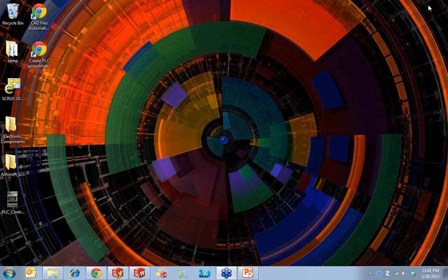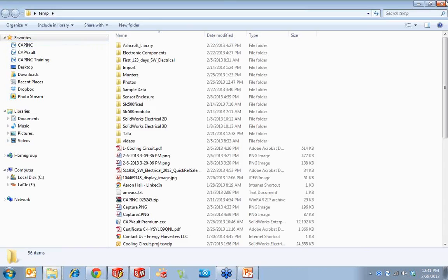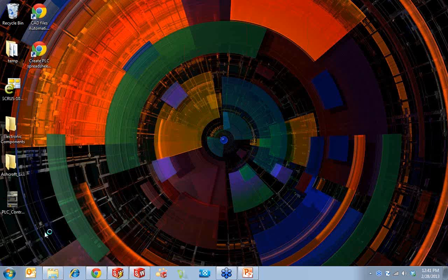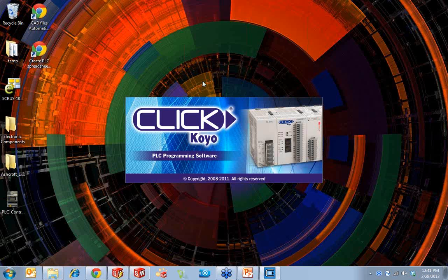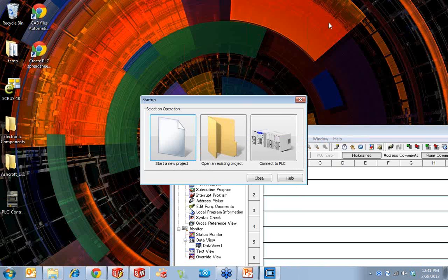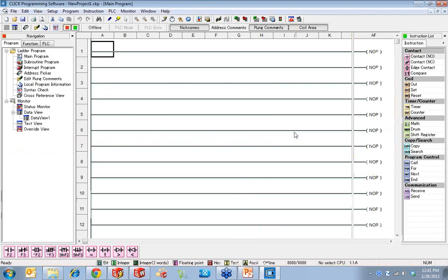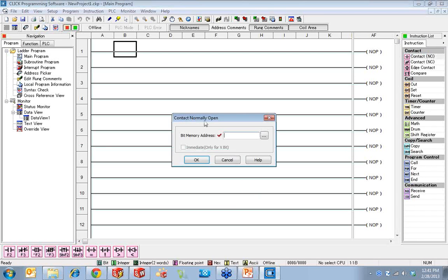And that would be achieved by, I'm not an expert at this application, but if you'll indulge me, I have picked AutomationDirect's PLC software in this case. And I could start a new project here and build my ladder logic for designing the PLC as far as what the functions are going to be, not necessarily the drawing of it. But I'm going to pick this. It's very much like an Excel spreadsheet where I'm going to say I want a normally open contact at a certain address.